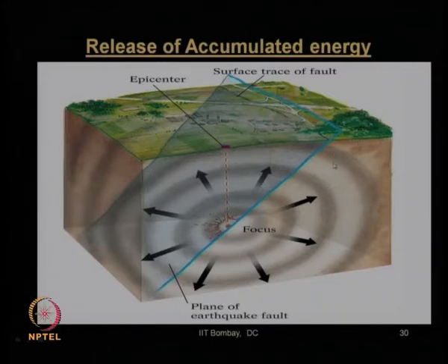So, geologists or seismologists generally give us the length of the fault, the depth of the fault and the area of the cross sectional portion of the fault as fault characteristics or fault database information, which are necessary, because otherwise, if you think the fault is located in this direction and consider the depth in this direction, obviously your calculation of fault characteristics will go wrong.